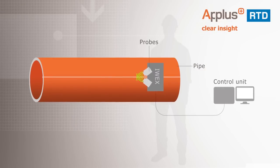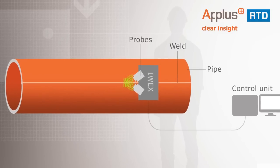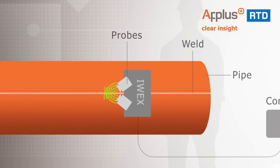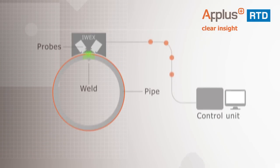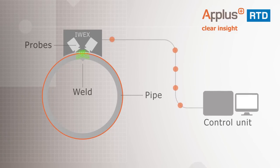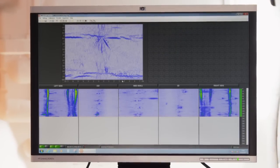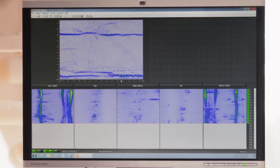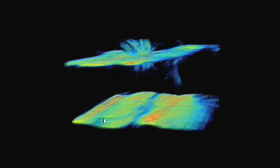An array of probe elements is driven alongside the weld. All elements consecutively fire a signal into the pipe. This generates ultrasonic wave fields, which are echoed back and received by the probes. This allows for more data to be acquired quicker and more accurately compared to standard ultrasonic testing. A fingerprint image is generated. The received data is processed using the IWEX algorithm and converted into a cross-sectional image, which can be represented in both 2D and 3D.